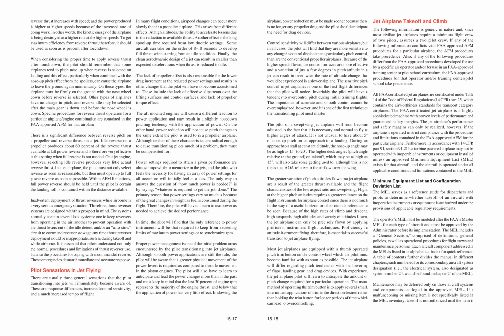The pilot will also have to learn to anticipate and lead the power changes more than in the past and must keep in mind that the last 30% of engine RPM represents the majority of the engine thrust, and below that the application of power has very little effect in slowing the airplane. Power reduction must be made sooner because there is no longer any propeller drag and the pilot should anticipate the need for drag devices. Control sensitivity will differ between various airplanes, but in all cases, the pilot will find that